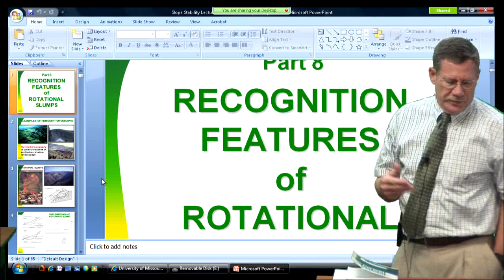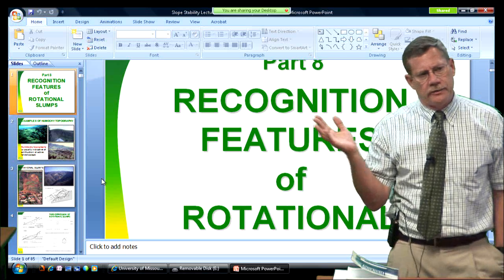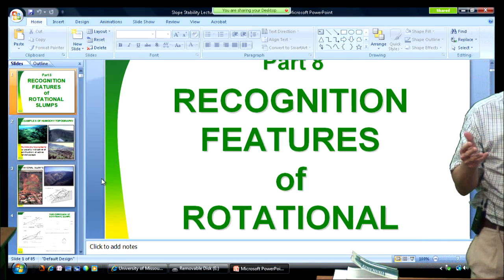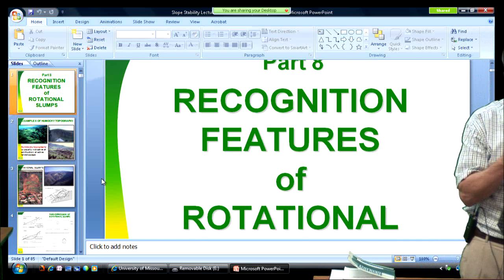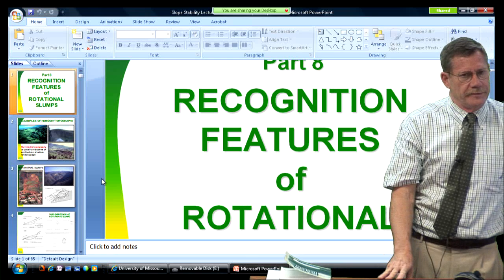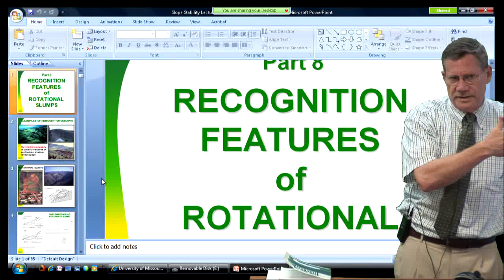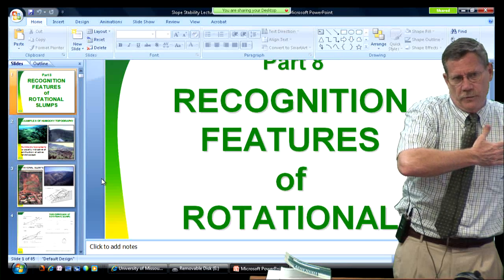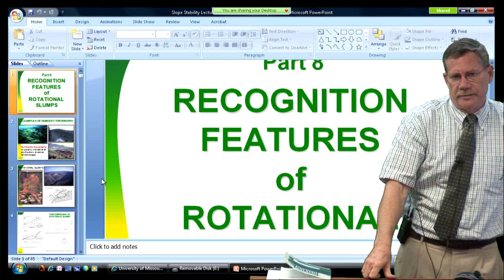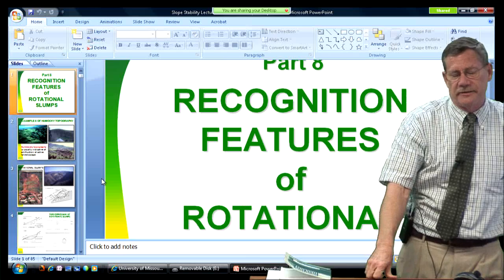writing assignment number 3. And that's the Walmart parking lot grading problem. And on that problem, you want to be able to do things like lay out what a 3% grade would look like across the parking lot area coming north of the building, and then realize when you cut your cross-section, you're not going to see 3%. You're at some 40-degree angle to the normal of what that 3% grade is. So the grade you're actually going to see on your cross-section is going to be something less than 3% grade.